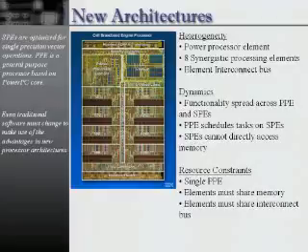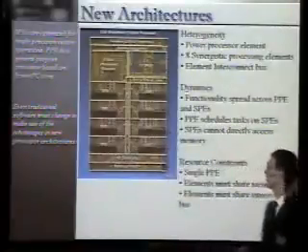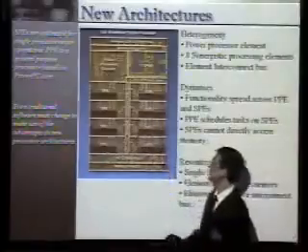So just to go into a little more detail, let's take the cell processor. If you look at it, it has heterogeneity, and on this single chip is a whole bunch of different things. There's a PPE, which is basically a PowerPC embedded on it. Then there are 8 synergistic processing elements, each of which supports different functionality than the PPE. They focus on vector operations, mainly for graphics. And then you have a complex interconnect bus to link all of these SPEs to the PowerPC. These 8 individual units can't directly access memory. They have to do it through this interconnect bus.